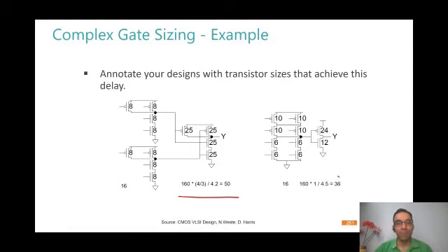Sir, for making the layouts of non-complex gates, if you are cascading one NAND gate after the other, I think metal layers would get blocked, right? At most you may need one metal 2 to make those connections. Use metal 2 only for that purpose. Okay, sir. So it should be evident when you show the layout.